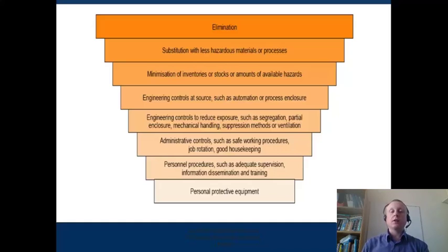And so all of your guarding should be interlocked with the operation of the machinery wherever possible. This isn't always practical, but it should also be quite difficult to remove the guarding, because it's one of the favourite things of employees to try to make their life a little bit easier for themselves. Then the familiarity with the process breeds contempt, in much the same way as the familiarity with the dangers of car travel breeds contempt for the risks posed by that car travel.